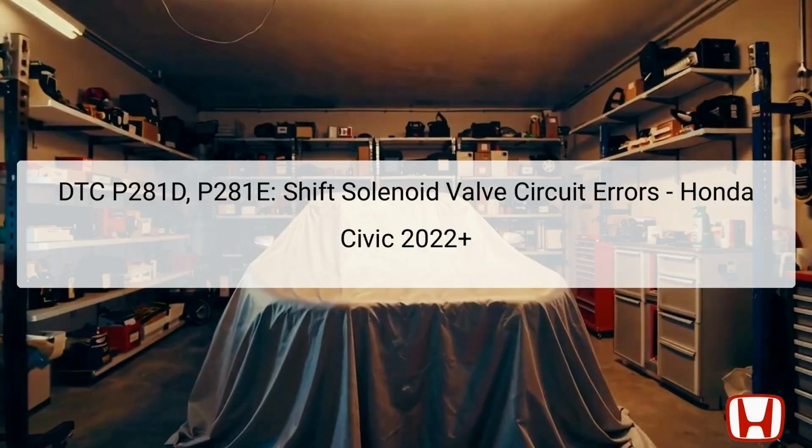The identified diagnostic trouble codes DTC P281D and P281E relate specifically to issues with the shift solenoid valve output circuit in the 2022-plus Honda Civic. DTC P281D indicates that the shift solenoid valve output circuit is receiving a low signal when the transmission control module, TCM, commands it to be activated. Conversely, DTC P281E suggests that the output circuit receives a high signal while the TCM indicates the solenoid should be off.